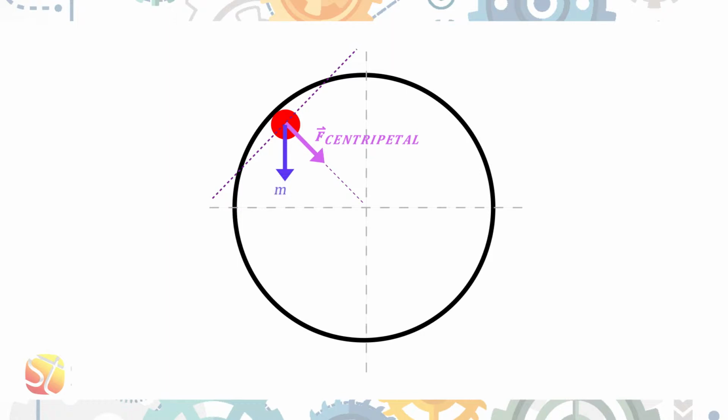To simplify our discussion and derivation, let us take a snapshot of the mill's rotational motion and let our entire bulk material be represented by a red point particle. During motion, the force pulling the red point particle to the center of the mill is the component of its weight. Therefore, we find that centripetal force is equal to the product of the red point particle's mass times the constant acceleration due to gravity, or simply g, times cosine of angle alpha as shown in the diagram. Now, for it to stay at the circumference, it needs to be counteracted by a force opposite of its direction, which is referred to as a centrifugal force.